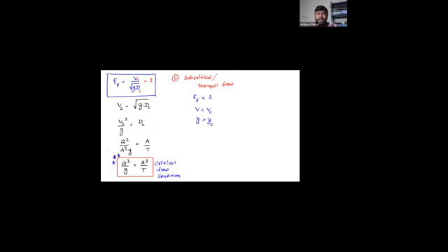Whenever the flow velocity is less than the critical velocity and the flow depth is more than the critical depth, what is y? Flow depth. What is YC? Critical depth. Then you are going to state the type of flow as subcritical flow.